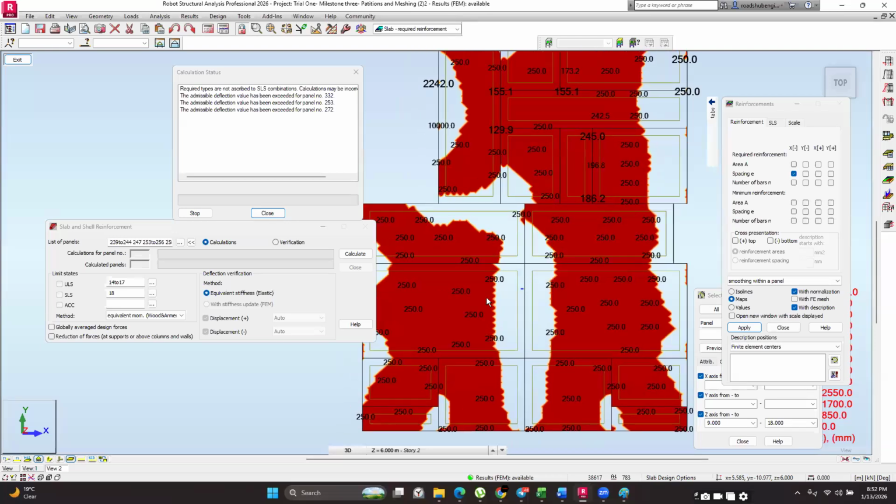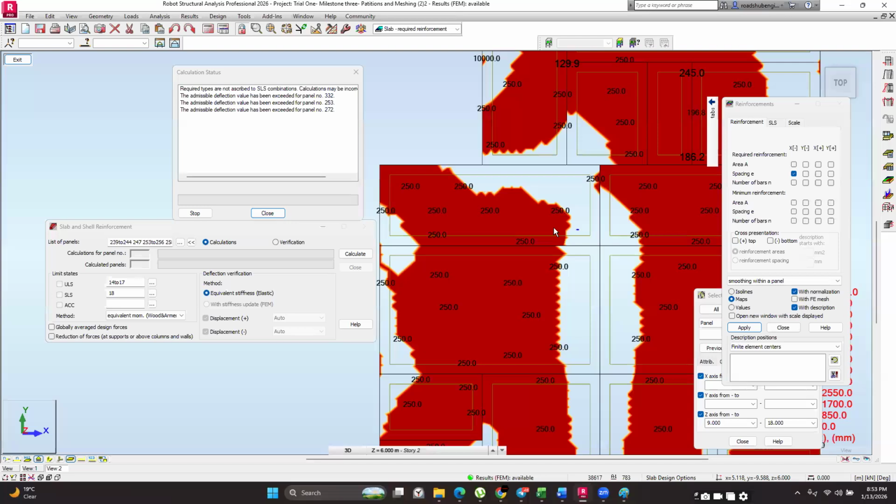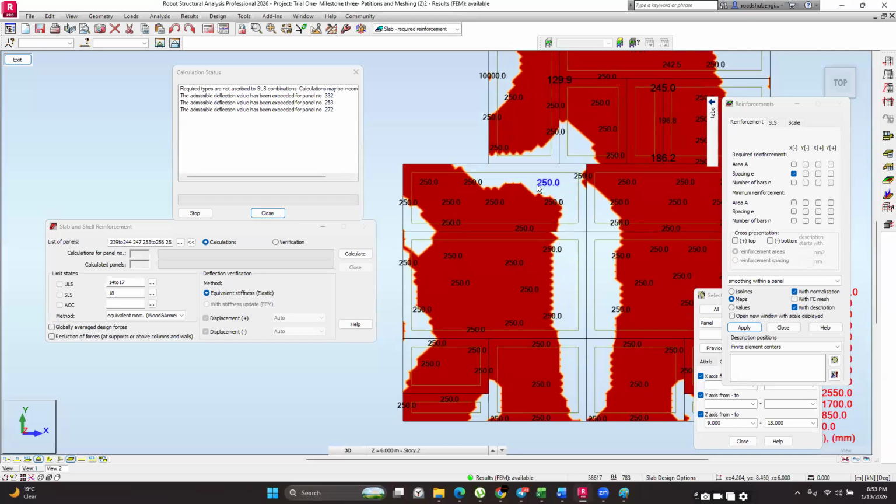in these areas. So for this one, you'd find that when lapping, it doesn't have to go into the next span by much. All you need to do is ensure that the lapping bars are 50 times the diameter of the bars. Okay, let me focus on design for now.